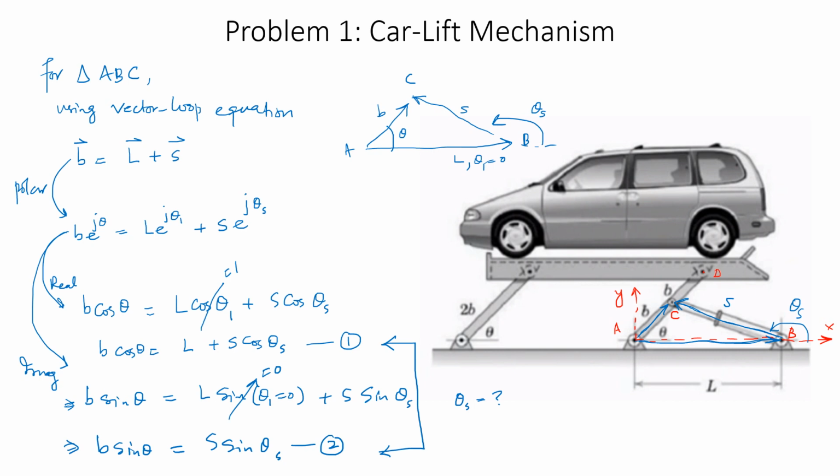So for that reason, S is something which I can readily identify. But theta S, the angular displacement because of this particular hydraulic actuator being pivoted over here, is not that straightforward unless you specify some special sensors like encoders over there. So in normal form, this is not going to be something related readily with the extent of or the kind of movement that we are going to have. So this theta S is not readily available. So I would indicate that: not readily available.